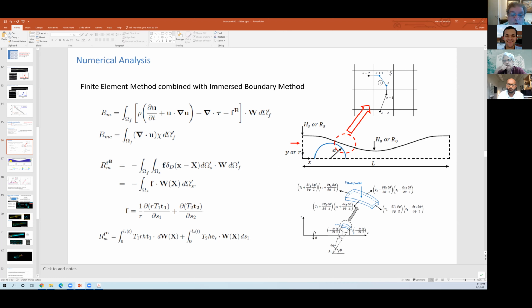Okay. So you also have a mesh for the free flow inside the capsule, because you're going to have the coupling of the 1D with the 2D, which is the body force, but then inside the capsule, it's a liquid too. To make it simple, in the model we assume that the viscosity inside is equal to the viscosity outside. I'm solving for the velocity field on the inside of the capsule also.